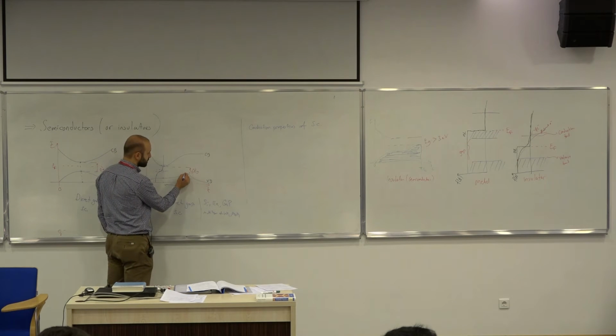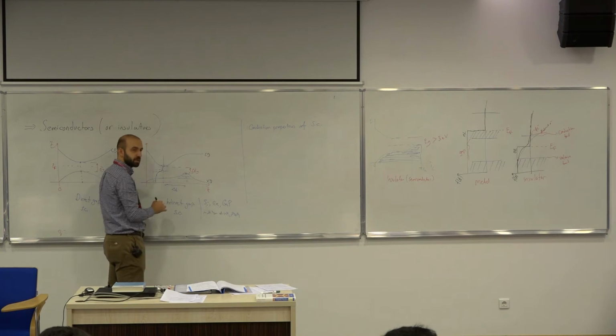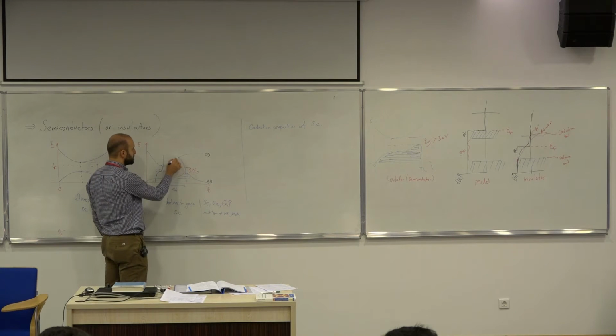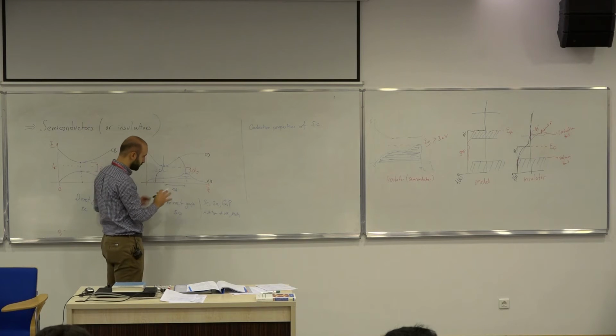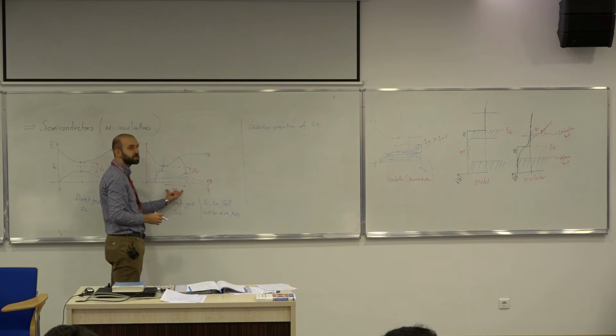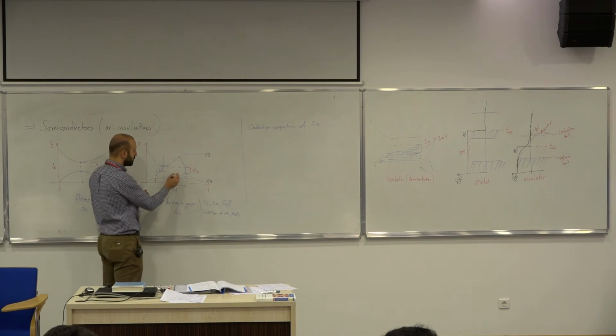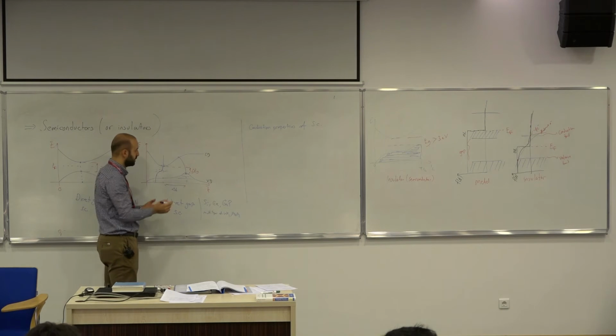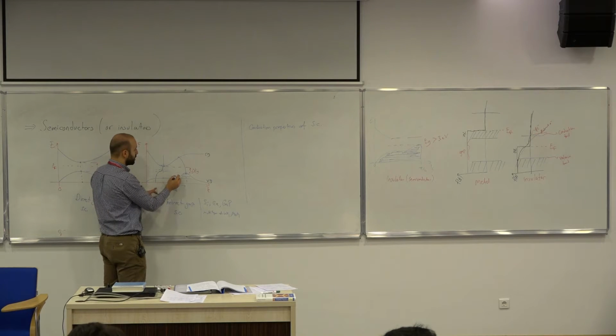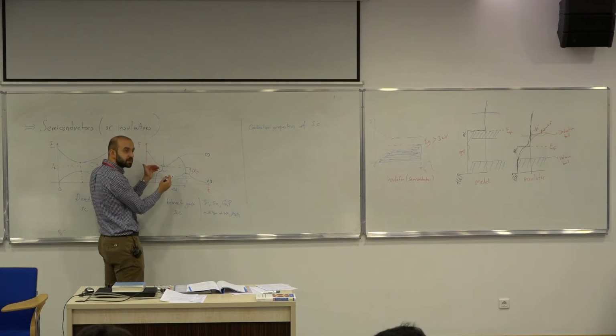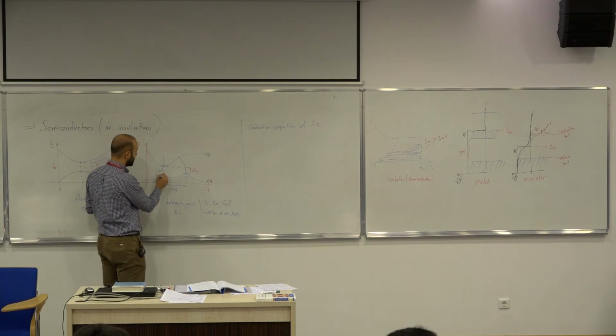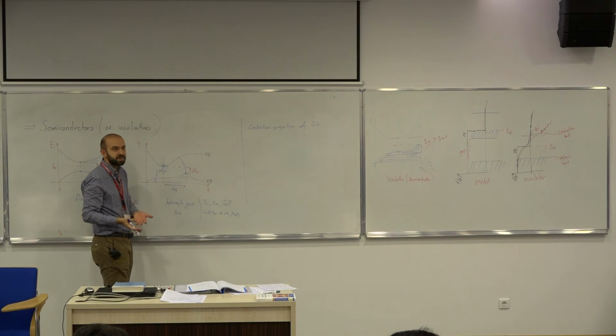is basically this. If you want to take one electron from the valence band and excite it to the conduction band, either you have to supply this energy so that it can make a direct transition, but it may not be allowed all the time, by the way, or you need to supply this momentum difference so it needs to scatter from something so that it can first go to an intermediate state. Because of the scattering, it will create an intermediate energy state, and then it can make a transition, which is an extremely rare event.